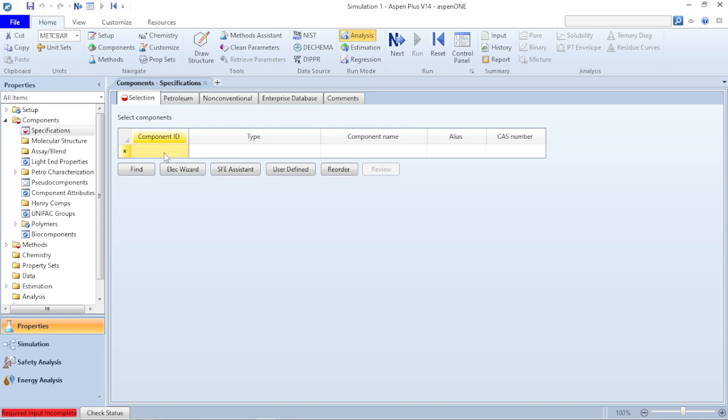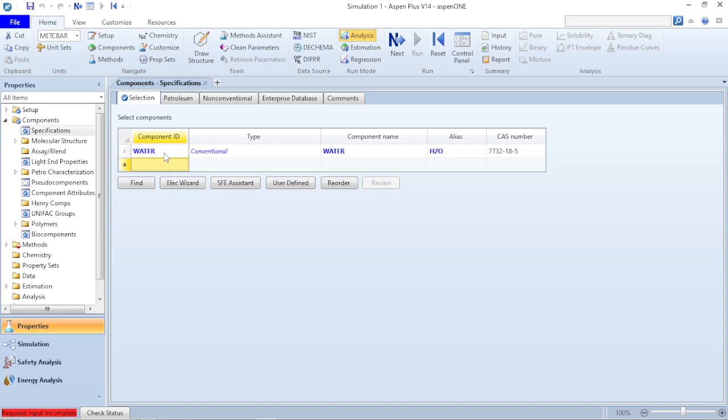So we select water as our component, so I just type in water. That's another way of putting my component in. And I leave it on conventional. Remember that's the standard liquid, right? Conventional usually is mostly the liquid form of water. And then the joy of Aspen Plus, which I must really add, is that it helps you to run simulations on solids.